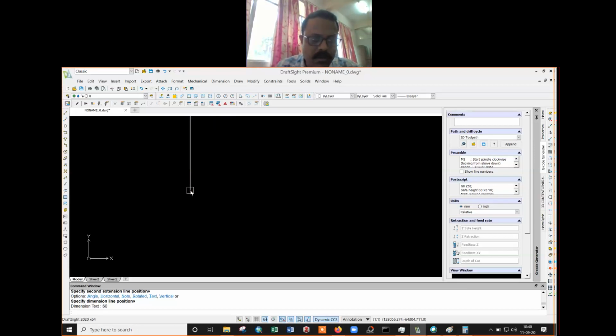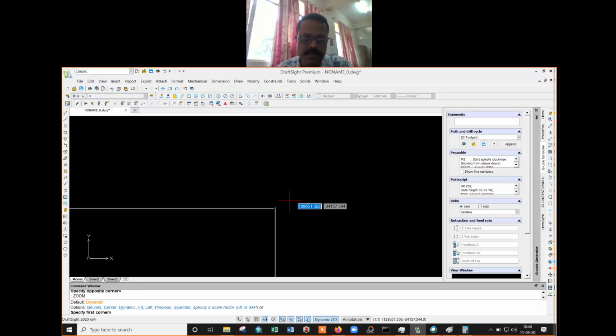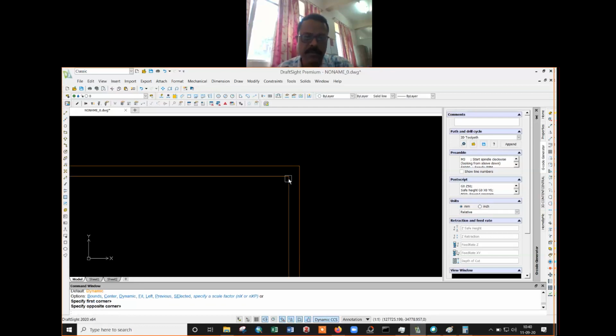And then together you can draw these two lines. Anyway, I will clear this thing in the next class. So this scale, if you can properly maintain, you can draw two lines, or even more than two lines in one stretch. So if you want to draw a wall or a plan of a building, you can just use multi-line to draw it. Okay, together with multi-line, we have another line called polyline.